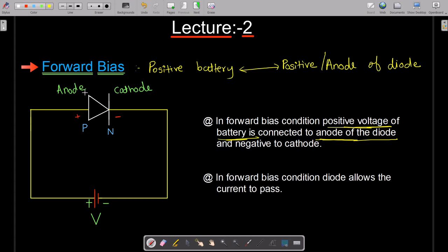So this is forward bias, and due to this, what will happen if you are providing a voltage greater than 0.7 volt? I told you why this voltage is 0.7 volt: because of the depletion layer. I'm not explaining the internal structure of the diode because I had already explained that concept in great depth in my course 2. So if you don't know this at this point, please go and learn it from course 2. Here the barrier potential, or the depletion layer, is 0.7 volt. Depletion layer is also known as barrier potential, it's one and the same.